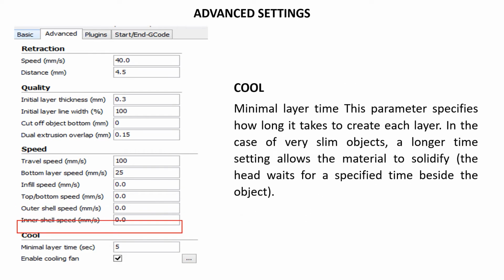Cool. Minimal layer time. This parameter specifies how long it takes to create each layer. In the case of very slim objects, a longer time setting allows the material to solidify. The head waits for a specified time beside the object.